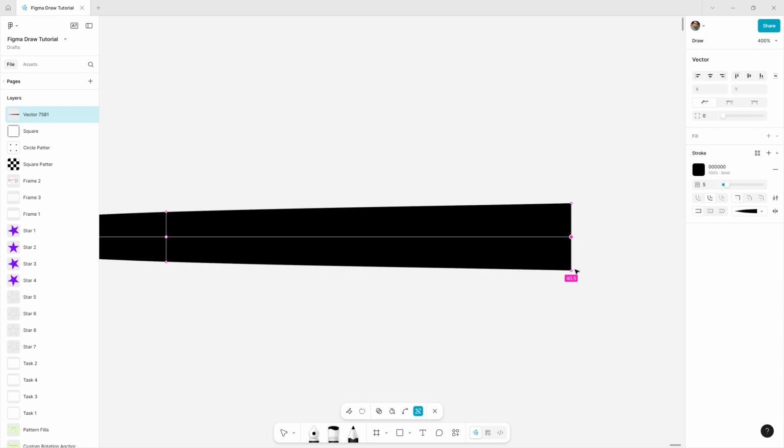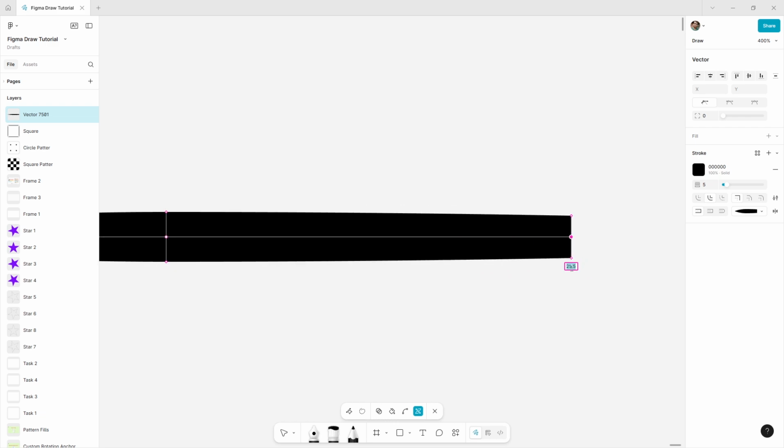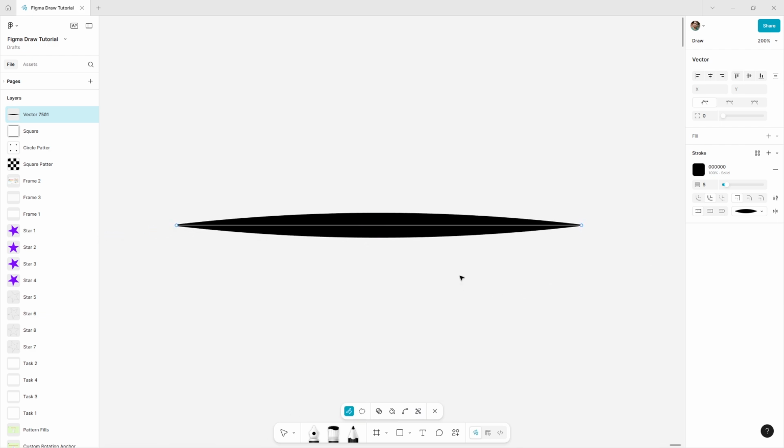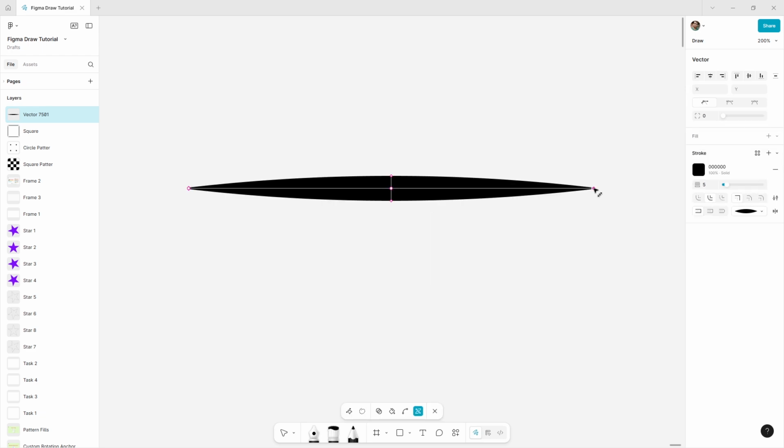Let's say you want something in between the presets, like a width of 1.5. All you need to do is click into the pink control box and type 1.5. Just like that. Done. Even better, double-clicking brings you into width editing as well, so precision editing is smoother than ever.